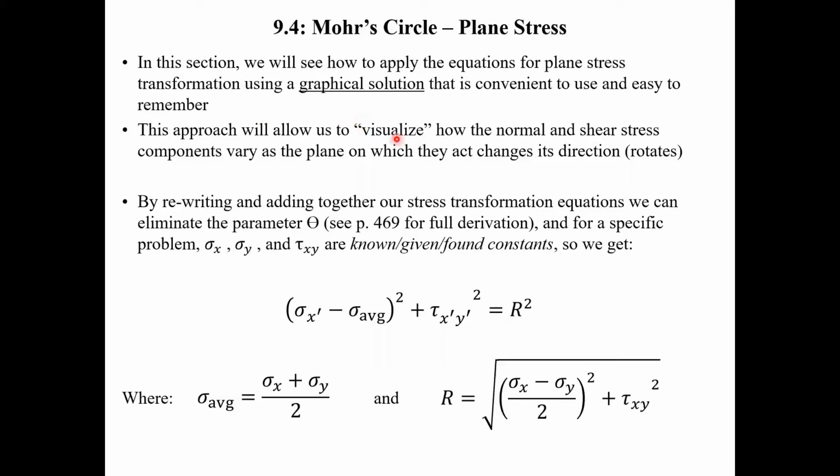It's also going to allow us to visualize how the normal and shear stress components vary as the plane on which they act changes its direction as it rotates about that z-axis, or whatever that third axis is. So if we think back to what those stress transformation equations were, if we do a little rewriting, add some stuff together, we can eliminate that parameter theta from the equations.